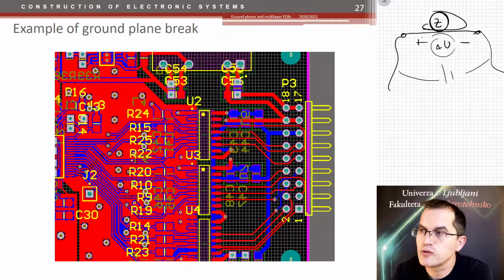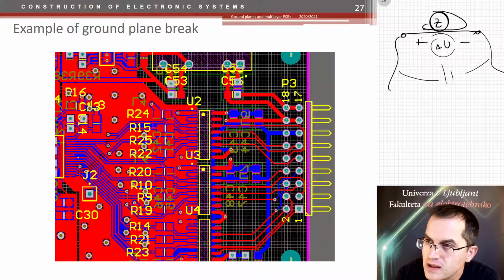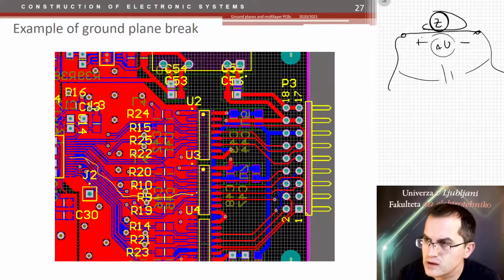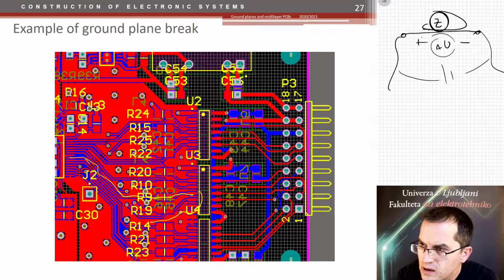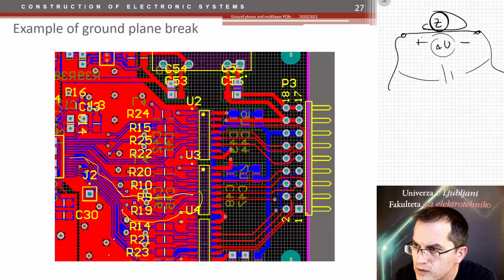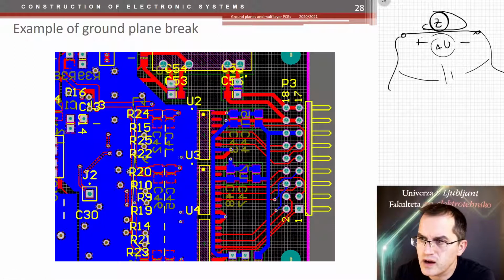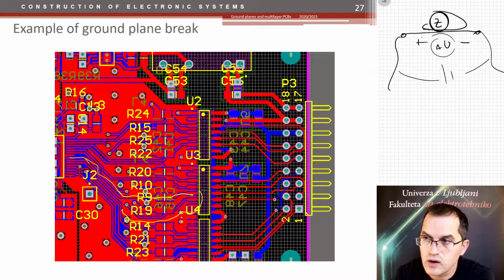So let me show you how to follow the tracks now. Let's say this is a source. The current starts here, follows this track somehow, I think it's here, going through here, finishing there. Now it goes to ground and then back. It comes to here, then it cannot go any further, but there are 1, 2, 3 wires here. Let me show how the situation is on the bottom. That wire is on the other side of the track, luckily, and these two are here. So the return current cannot go there. It actually has to go on top.